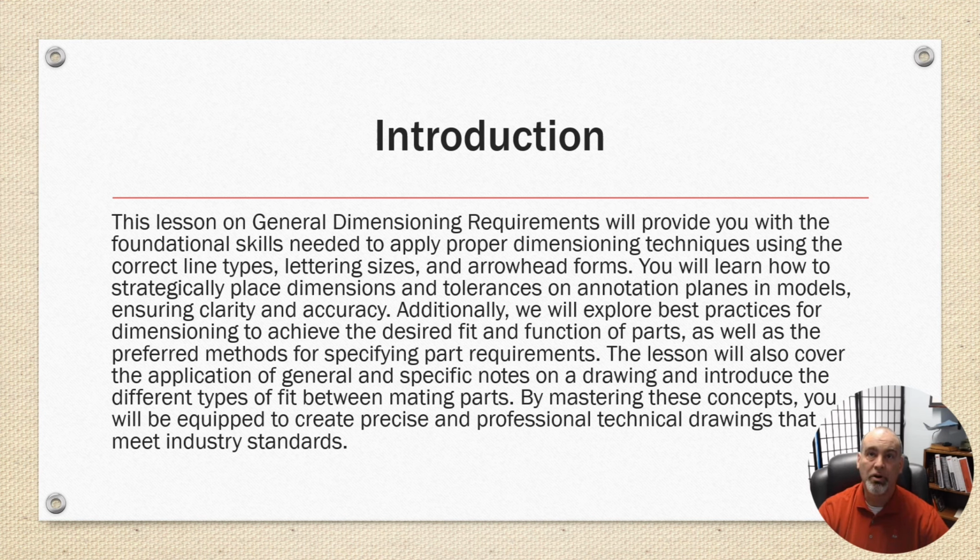The lesson will also cover the application of general and specific notes on a drawing and introduce the different types of fit between mating parts. By mastering these concepts, you will be equipped to create precise and professional technical drawings that meet industry standards.